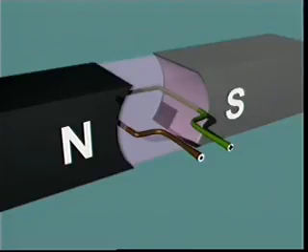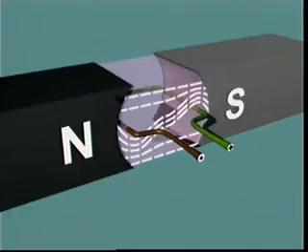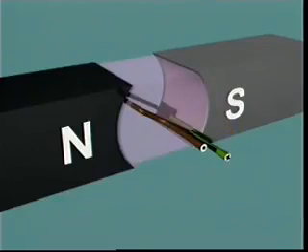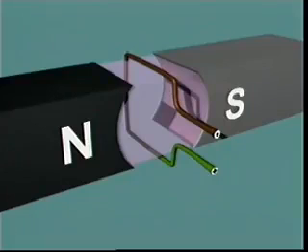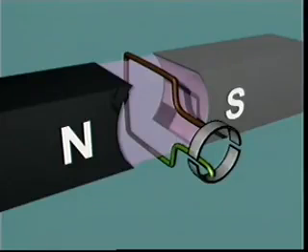In this position, when current flows through the loop, the stationary magnetic field is distorted and the lines of force try to straighten. This forces one side of the loop up and the other side of the loop down. The motor effect causes the loop to rotate until it is at 90 degrees to the magnetic field. To continue rotation, the direction of current flow in the conductor must be reversed at this static neutral point. A commutator is used for this purpose.